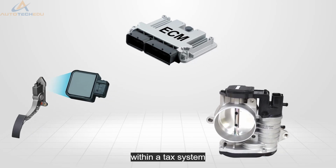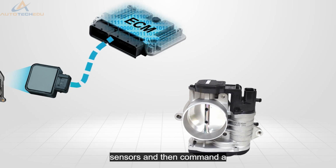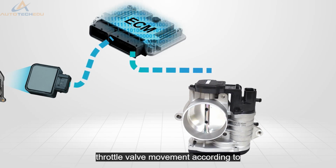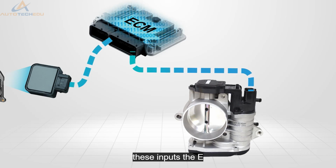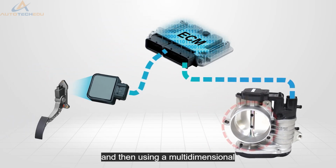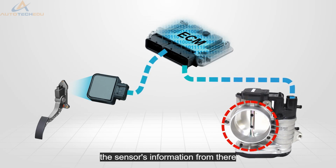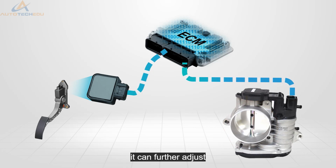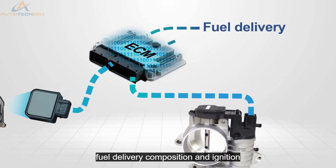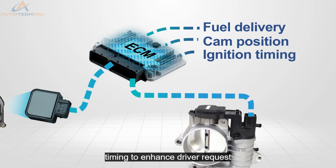Within a TAC system, the ECM's role is to process data received from the APP sensors and then command a throttle valve movement according to these inputs. The ECM interprets the data and then, using a multi-dimensional map, plots the optimal throttle valve angle based on the sensor's information. From there, it can further adjust fuel delivery, cam position, and ignition timing to enhance driver request torque output.